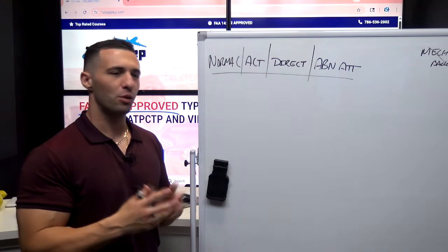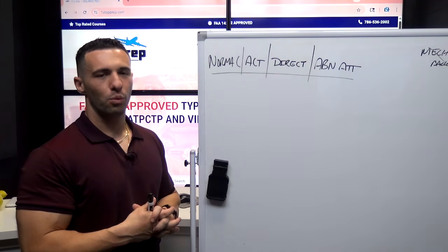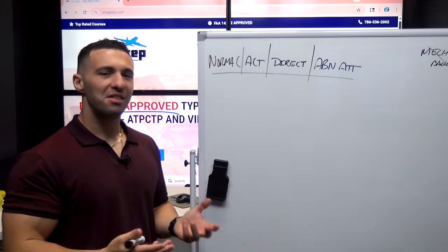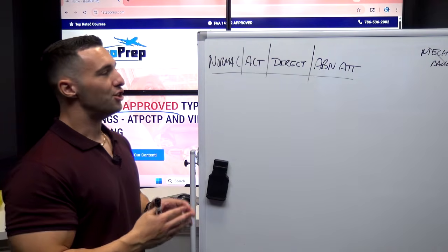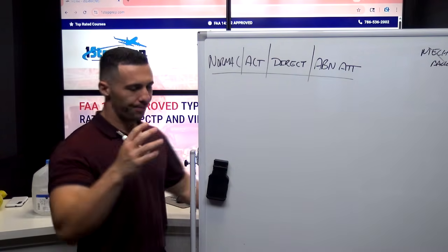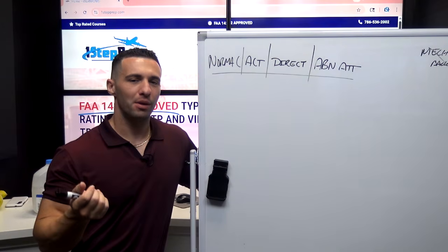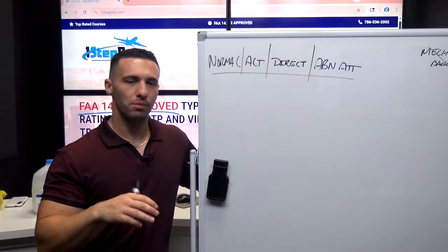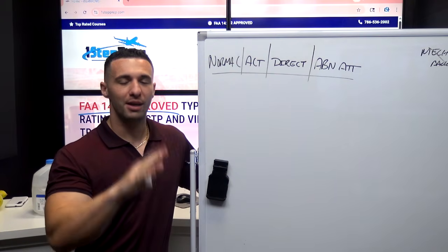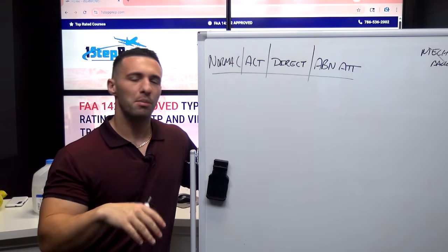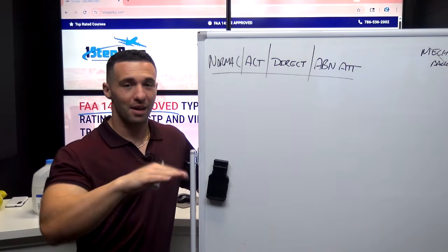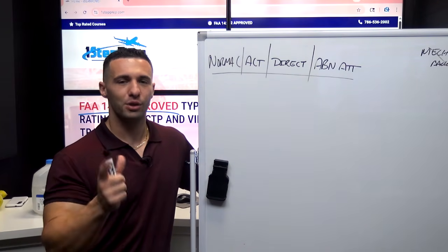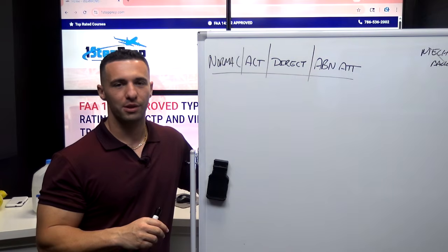This is where the jet has quickly exceeded the envelope, plus 30, 67 left, right. It's exceeded this envelope, and generally the roundabout way that I remember it is it's basically like a double of the envelope. If I go, say plus 60 nose high, it's really more than plus 50. But if I double the envelope, 67, if I double that, I go to 134 degrees. That's certainly more than 125, which is the value. I got to exceed 125 degrees of bank.